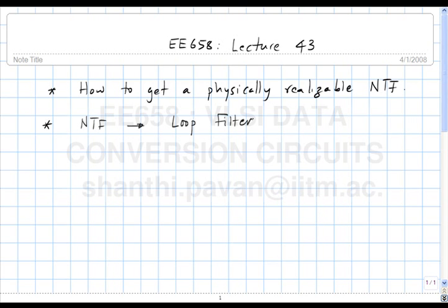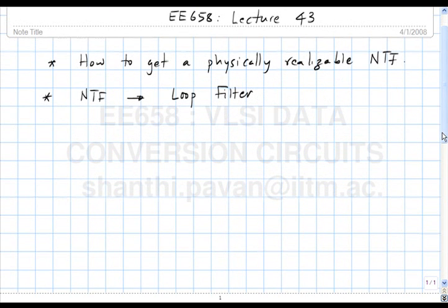Alright, and in general, if you have an nth order modulator with all zeros at omega equal to 0 or z equal to 1, we found that you should have at least n integrators in the loop filter, and there will of course be feed forward branches which add the outputs of various integrators and realize the loop filter output. So the next thing that I want to discuss is the mechanics of actually, before I go there, another thing that we discussed is one way of finding